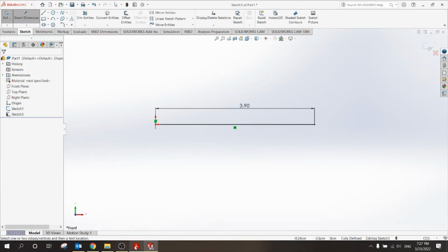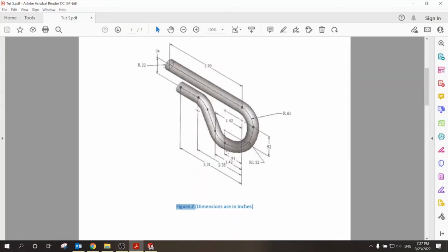And then I have these curves, which are defined by the points. So I have to create a small curve with the radius of 0.6, and then another segment, and the points connecting the curves are given by the x-axis and y-axis. But for now, let's focus only on making the sweep.